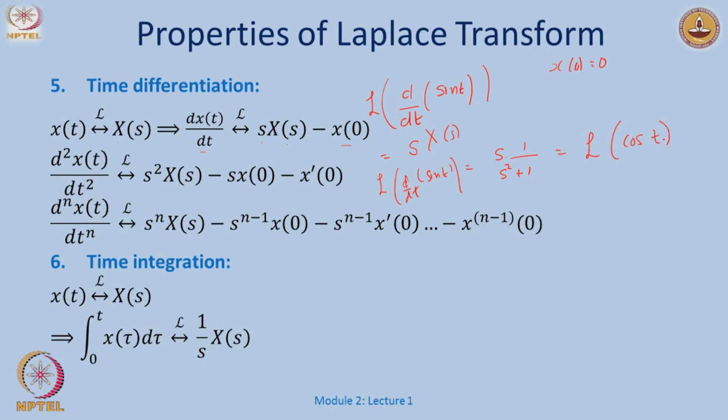Okay. Similarly with the time integration, right. So, if I have a signal and I integrate it from 0 to t, this is just like replacing it by 1 over s. Okay. You can just do the reverse of this example, and that will be kind of obvious here.